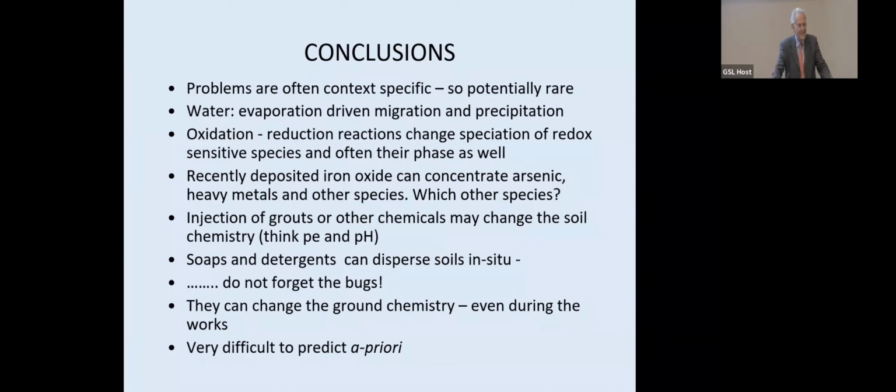Are we incorrect in that all the submersible pumps we use are almost universally stainless steel? And the Rolls Royce of well screens are stainless steel. If you've got iron slimes, perhaps not. But you need a little bit of acid to dissolve the material.